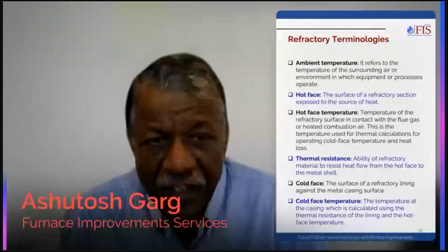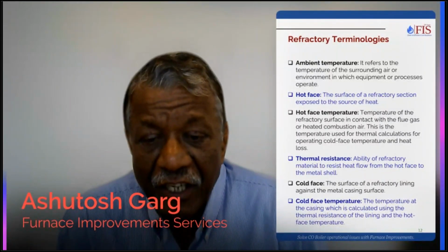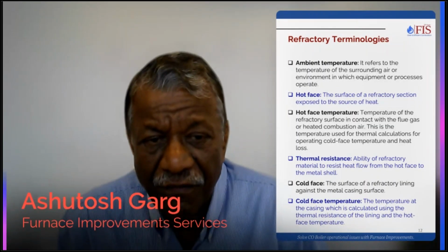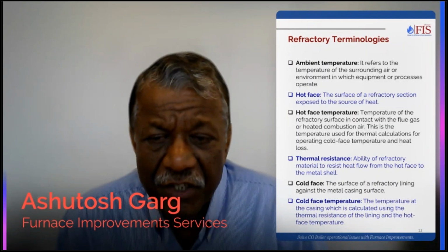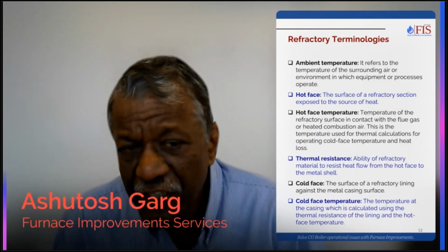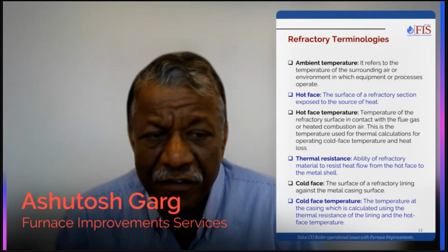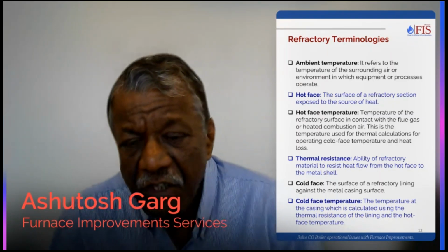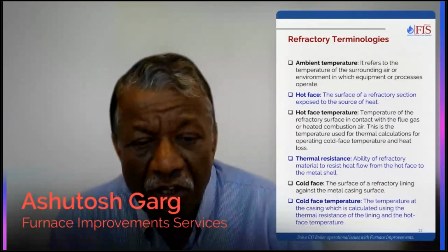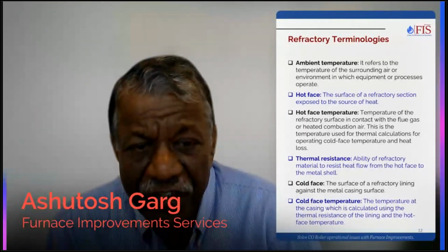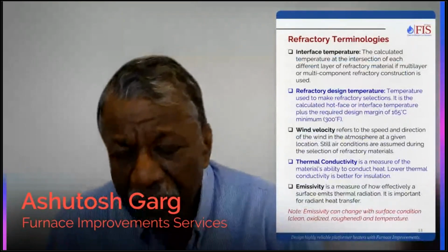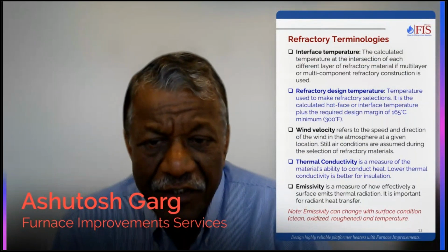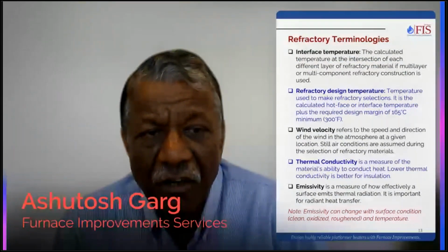Hot face is the refractory exposed to the furnace or flames. Hot face temperature is the temperature of the refractory. Thermal resistance, cold face temperature. I'm not going to go over all of these, but I suggest you go through the API 560 document and try to understand these different terminologies.